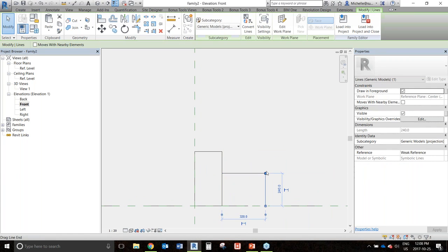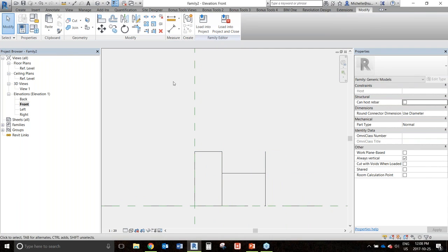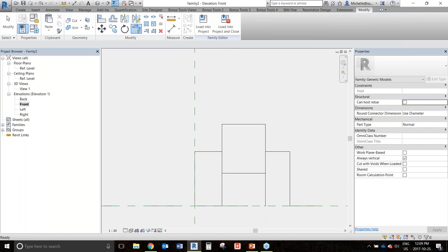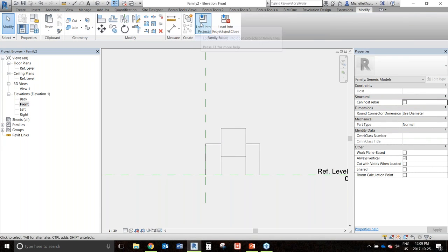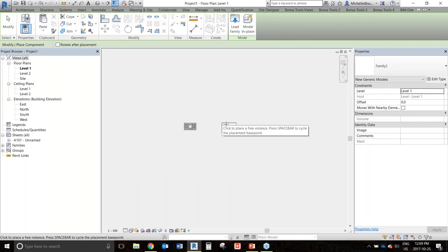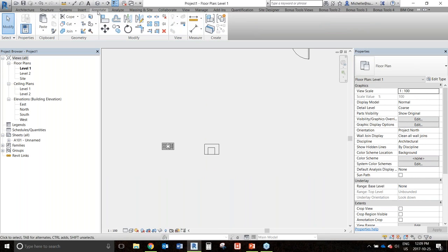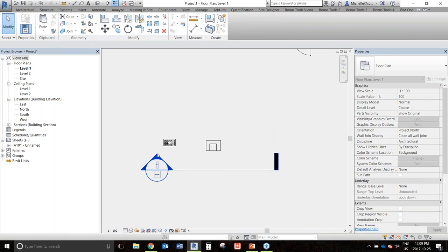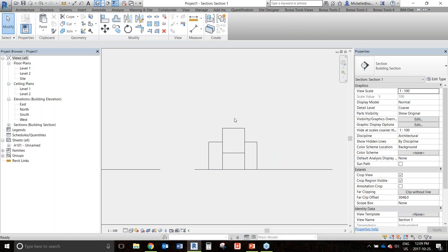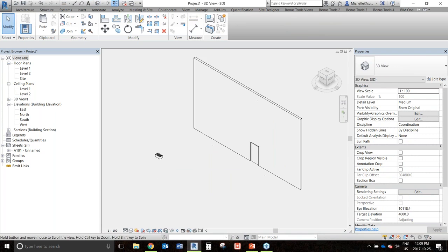And of course you're going to go through and make sure that this is showing at the right scale and all that jazz, but for this exercise you'll get the idea. So you draw what this needs to look like in elevation. Very nice chair. And then when you're loading that into your project, you'll see that there's nothing that exists in 3D, but you do get the plan representation, and if you're showing an elevation of this, you will get the elevation representation without having to actually do any modeled extrusions or anything else like that.